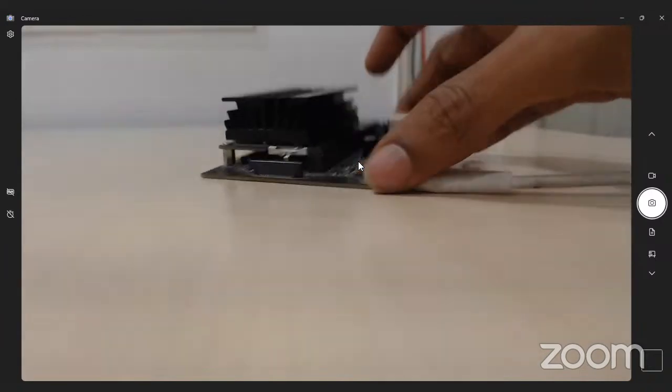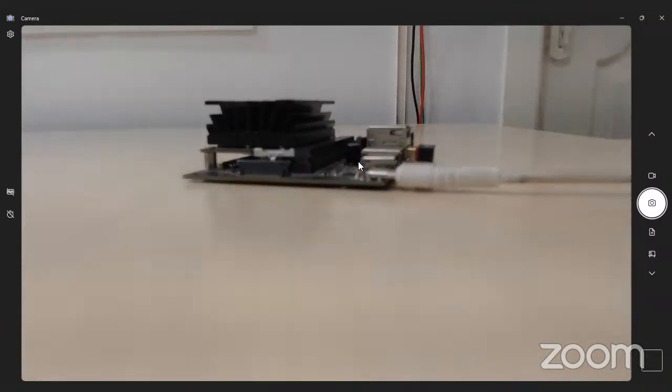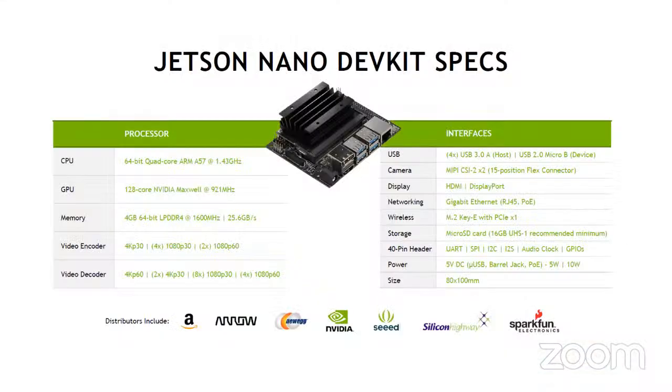So this is basically, you can say, a CPU. To use it, like any other CPU, we need a monitor and a keyboard and mouse. We can connect the monitor to the HDMI port, and you can connect the keyboard and mouse to the USB connectors. So these are 3 essential things you need to get started with the Jetson or any kind of single board computer.